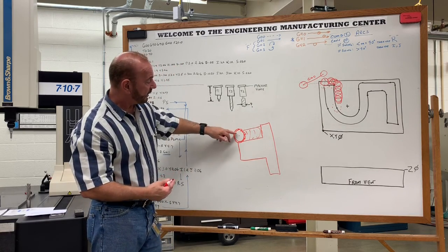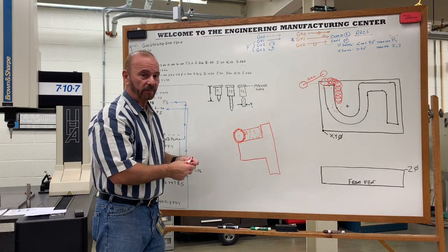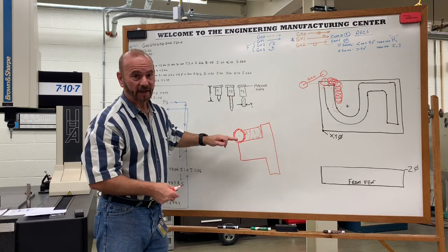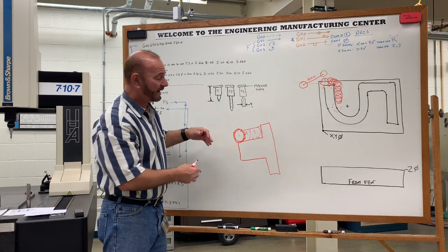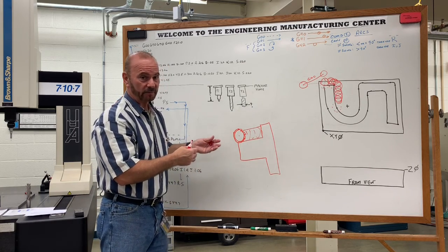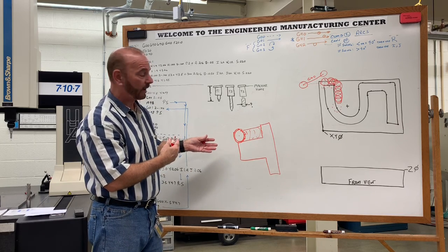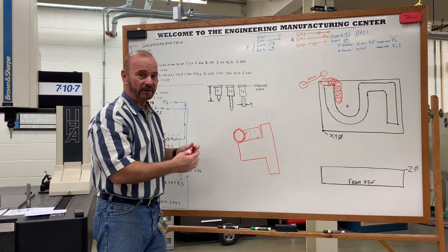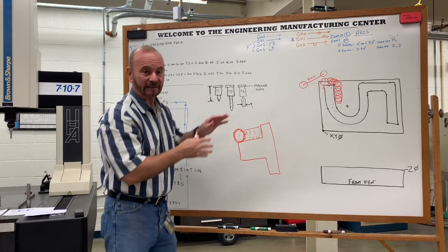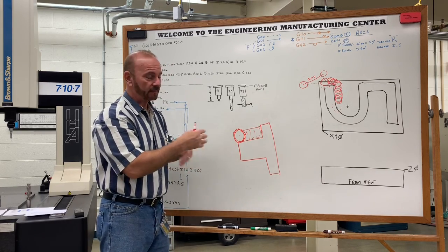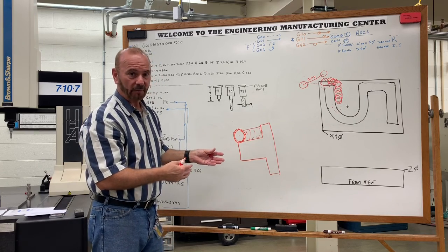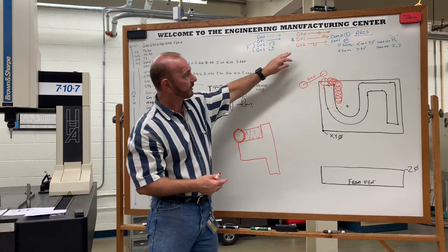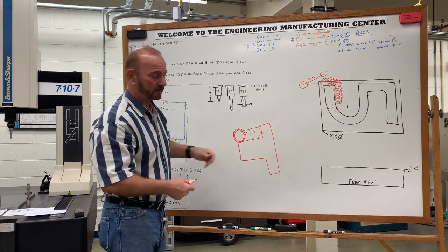But because these cutters are also made out of very hard materials, typically what happens is the cutter can't withstand that type of force that's being placed on it, and it can shear or break, and sometimes those pieces can fly right back at you. And I've even seen on looser tables where there's play in the table, where the table actually makes a leap. It runs away from that person, and that just amplifies the problem. So in order to get around that, we use the conventional cutting method, cutter right, to take these larger cuts.